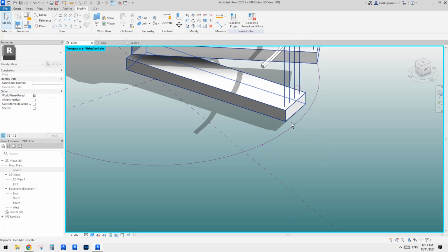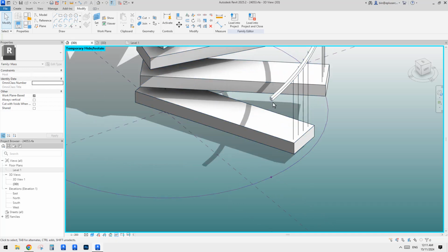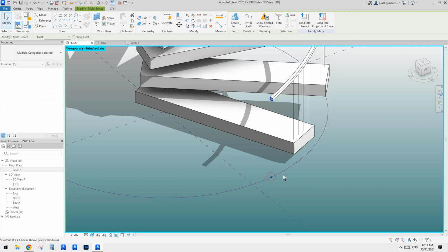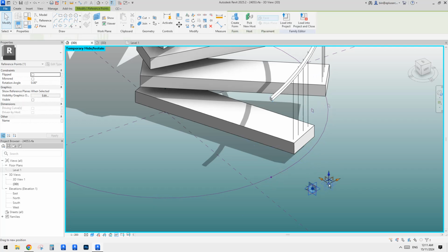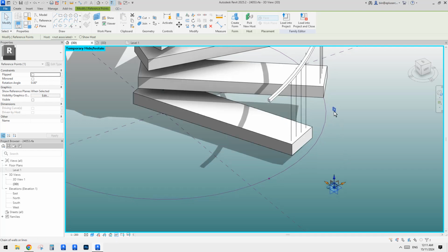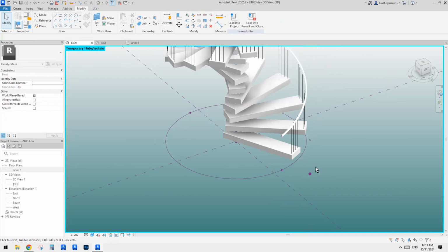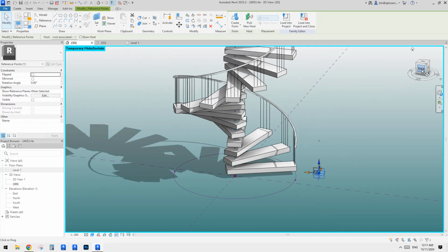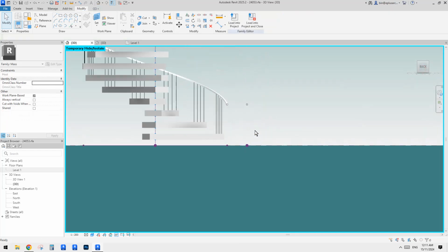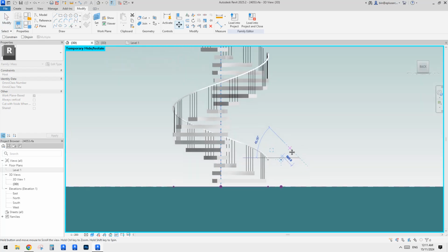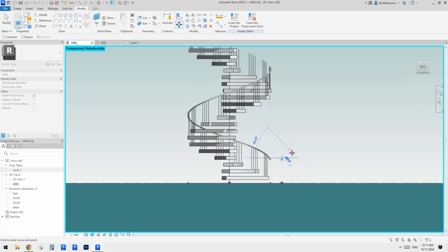So now I know that I need to tap once. Select this one, move the cursor onto this, tap once, control select, CC. Now again, see? So this means these profiles being placed are based onto this point. Okay, so now let's try. What I'm going to do is move this one up by 2340, and then we come here.